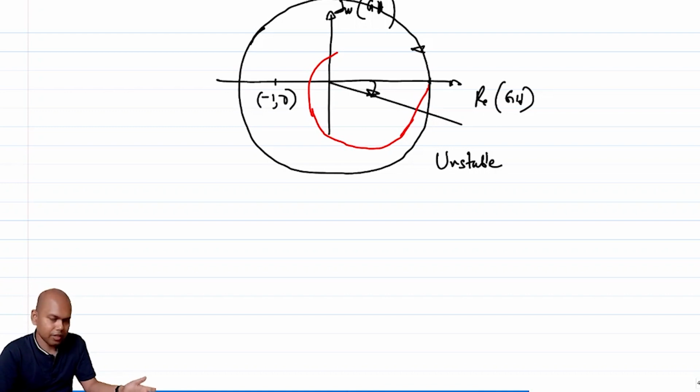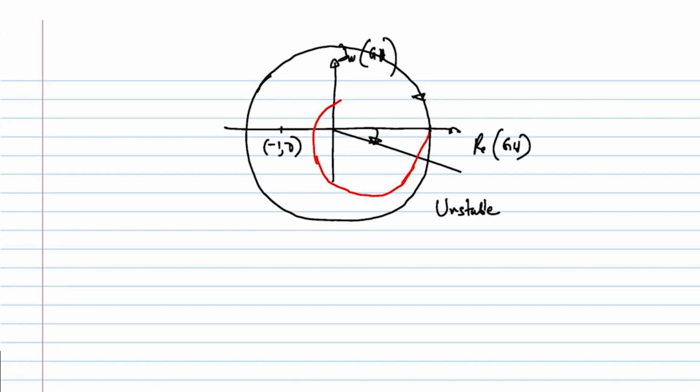And a third thing that we saw is that if there is a feedback loop and you have delays due to a transmission line in it, it can also lead to instability. We'll talk about more formal ways of dealing with this stability analysis using S parameters when we talk about power amplifiers later on in the course.